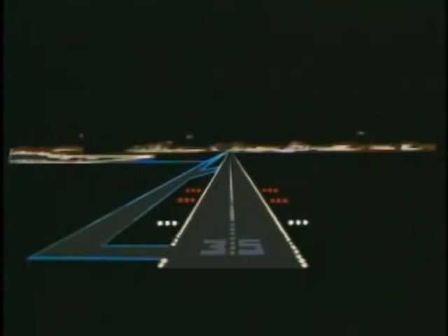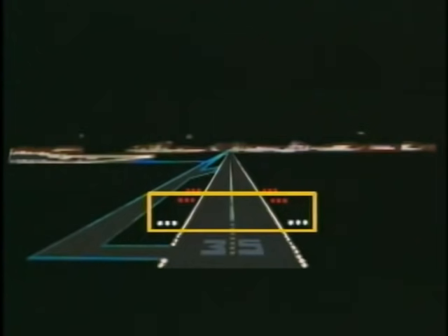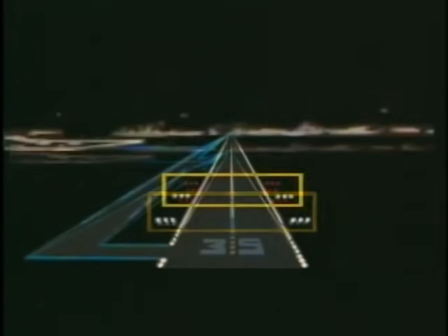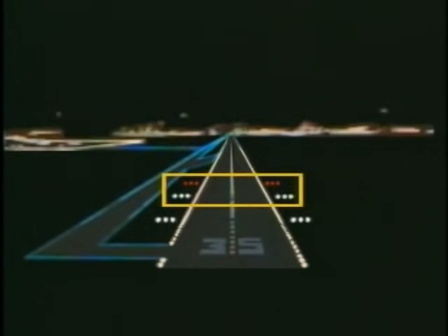Some airports have a 3-bar VASI system that provides 2 visual glide paths to the same runway. The 2 near bars give you the same glide path indications as the standard 2-bar system. The glide path formed by the 2 far bars is used by high cockpit aircraft and is about 1/4 of a degree steeper than the other glide path.